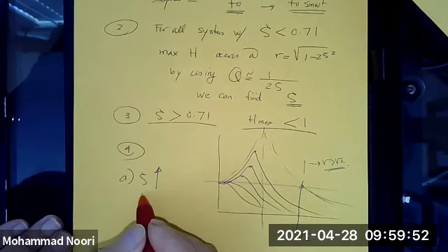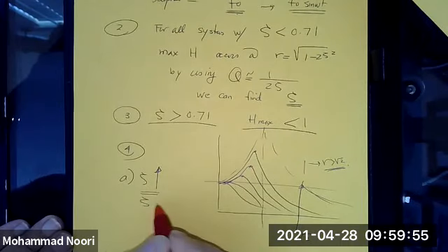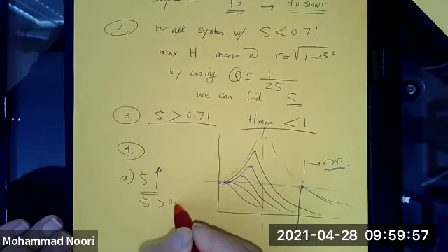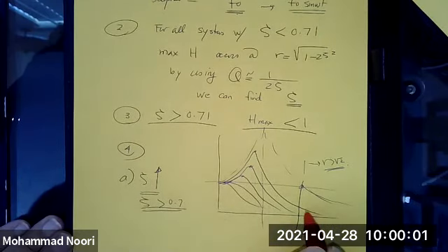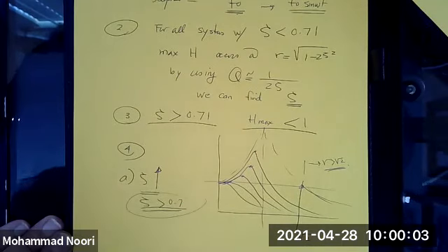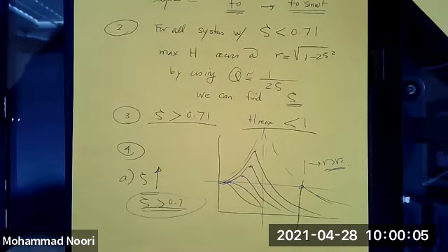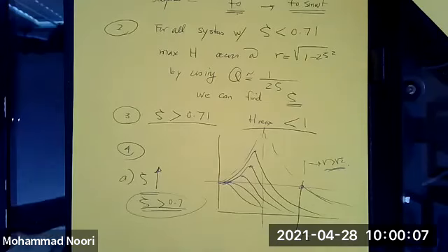Of course, there's a limit to that, because if you increase it to the point that zeta goes to 0.71, you are definitely guaranteed, but this may not be a good idea because it may result in too much energy dissipation or heat or whatnot.